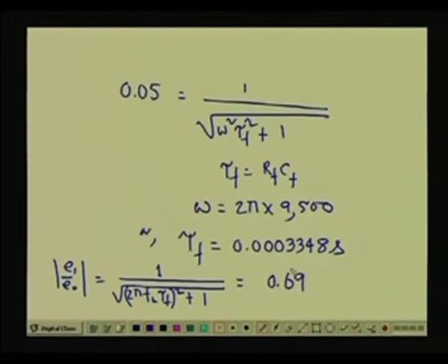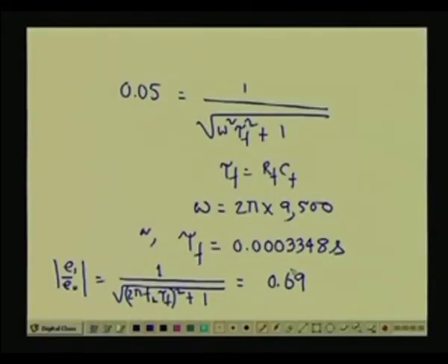Thus, we see that the high frequency portions of the Xi will be distorted considerably, right. So, the high frequency component of this Xi, that means the movement Xi of our LVDT core, will be distorted considerably. So, the inference is that this type of first order section will not be suitable for this type of application. So, let us take a second order section, right.